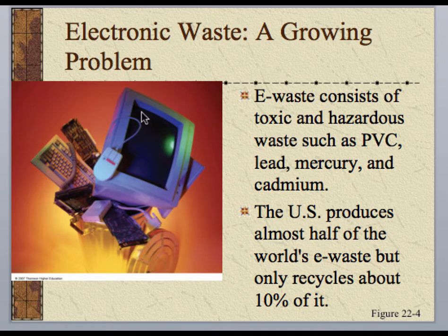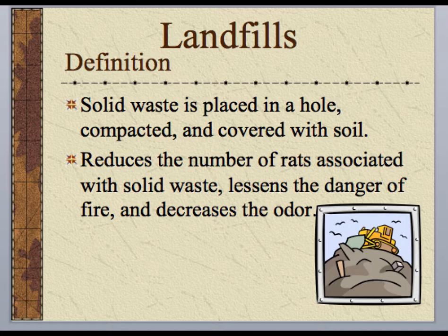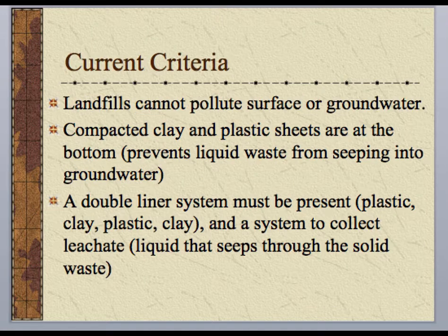So where do we put this MSW? We put it in landfills in the United States. Let me get to that slide. Solid waste is placed in a hole and covered, and we're going to look at that structure in a minute, so I'm going to go very quickly on this one. The current criteria is that landfills cannot pollute the surface or the groundwater, and they have to be capped. They have to have clay in order to decrease the amount of leachate, which is the nasty, polluted water that seeps through.